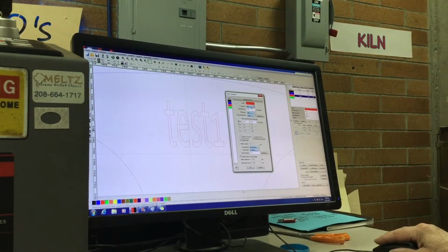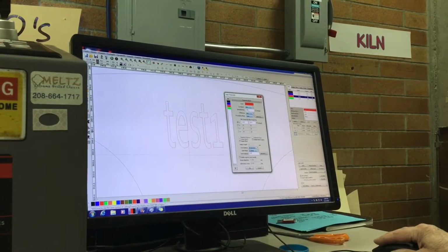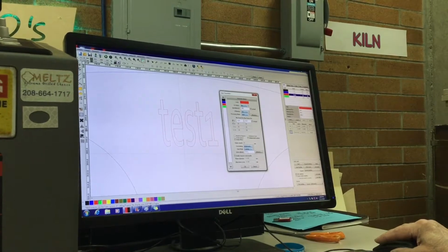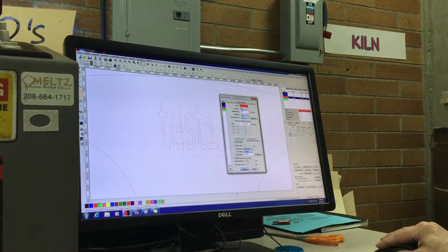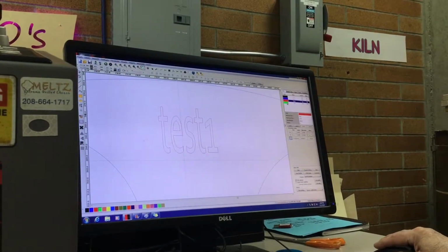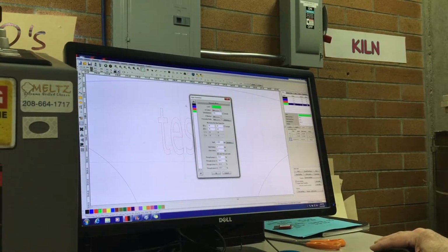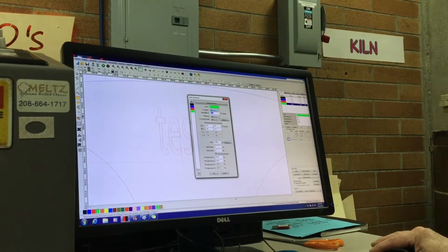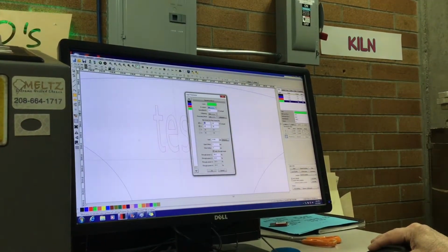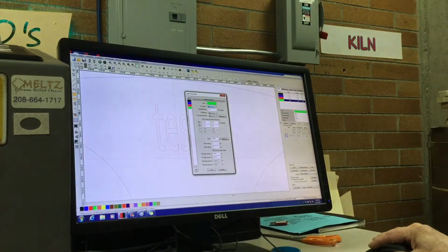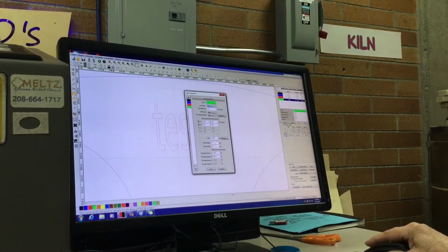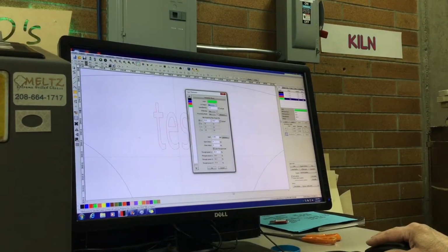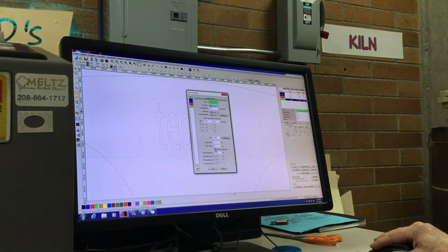So we're happy with these. This is our typical setting for a scan: 200 millimeters per second, something like 15%, 0.2 of a millimeter for the interval, and say OK. And then the very last thing we're going to do is cutting around the outside. We can use the same numbers that we used for the first one, which were 9 and 95, and we're setting both minimum and maximum power to the same. We only have one tube in here, so we're only setting it up for one, not using laser through.